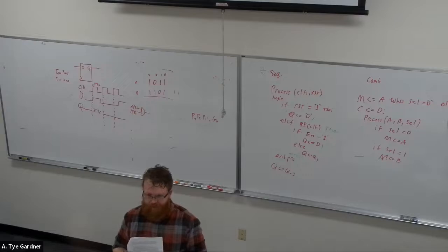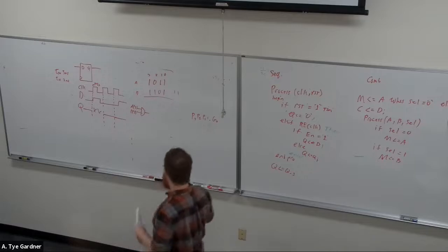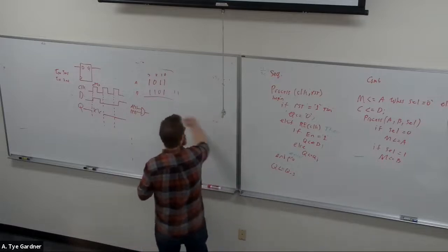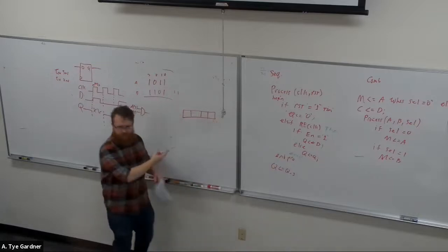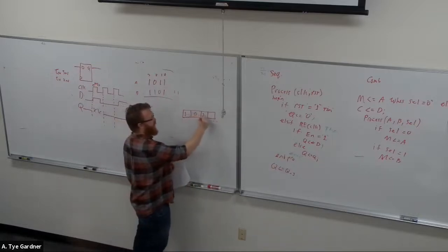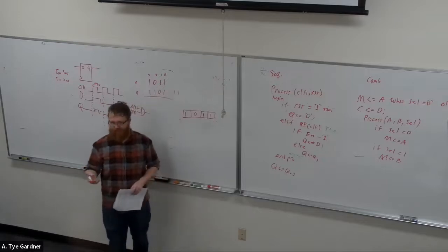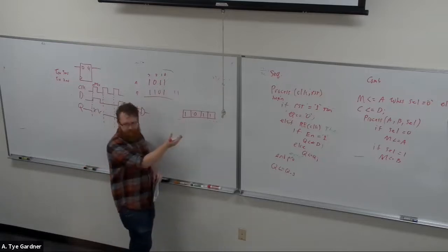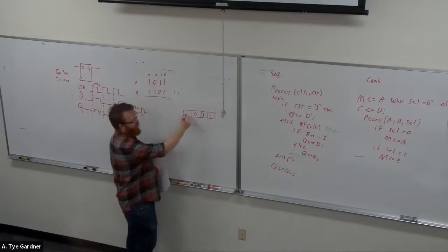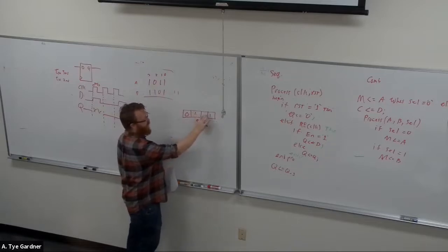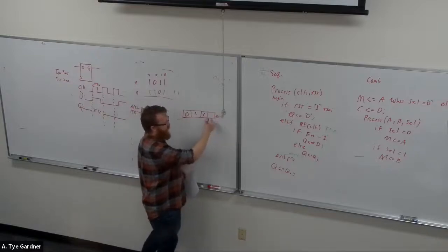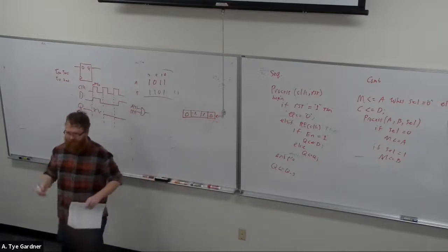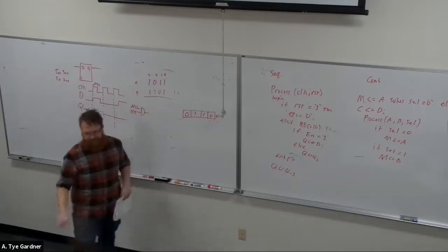I did mention them, but a shift register is what it sounds like: each rising edge of the clock, it takes the values and just shifts them over. So if you imagine a register, it stores values in it, and I tell it to shift, it just moves them over. Say we shift left, for example, this one gets thrown away, the 0 comes here, this one comes here, this one goes there. And now whatever is put at the input can get shifted in, right? That's a new value. That's all a shift register is doing. It turns out they're really easy to design.